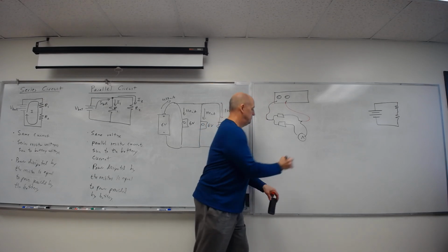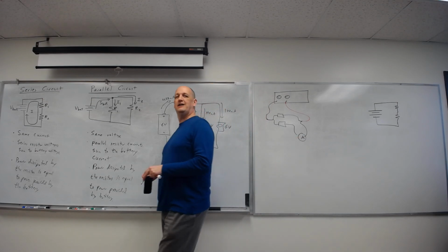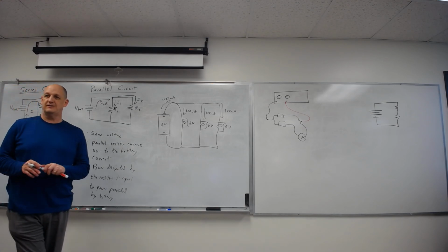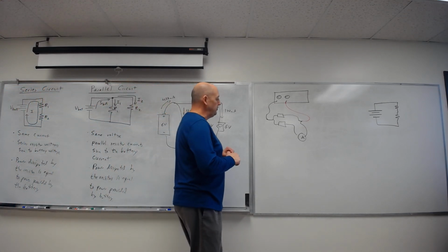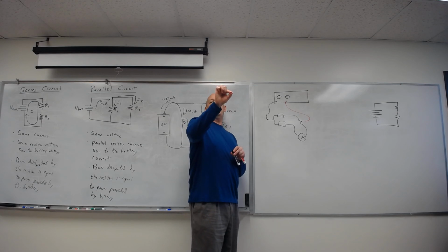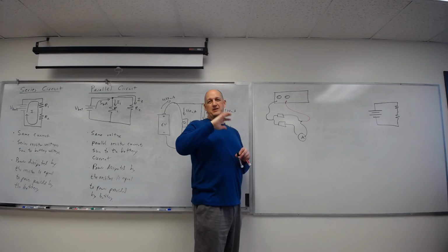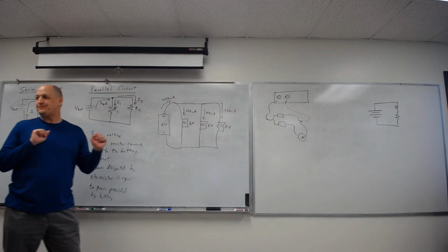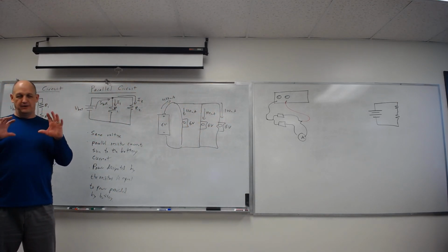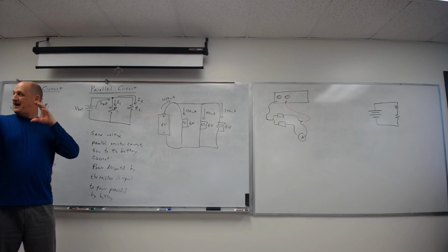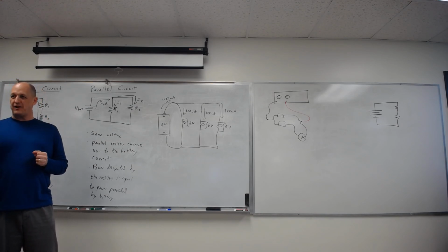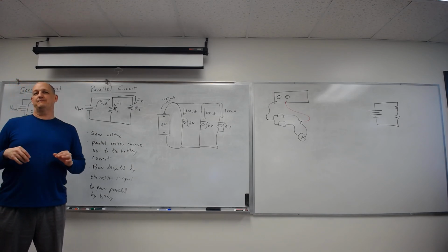So it's just measuring the current for that single resistor. Anytime you want to measure current, you only break the thing you want to measure through. I noticed a lot of this last week, a lot of people, and by the way, it's happened every semester, so it's common. Current measuring is tough. I think getting the idea that I have to put the meter in makes sense, but how do I actually physically remove it? You have to do it so everything else is still connected except for that one element you want to measure, and then you put it back in.